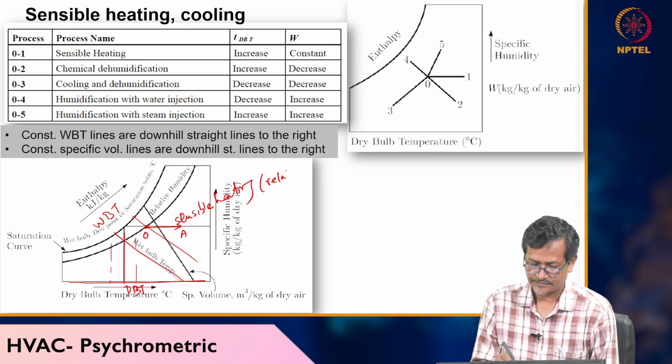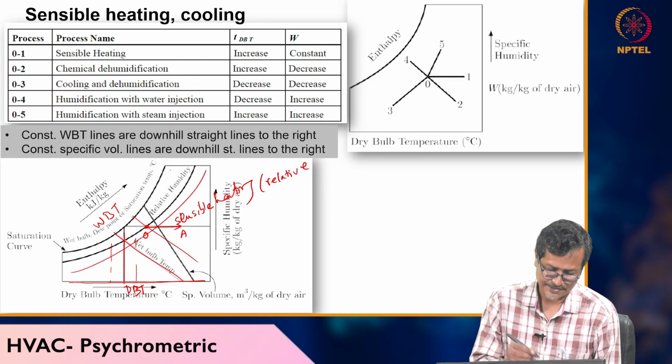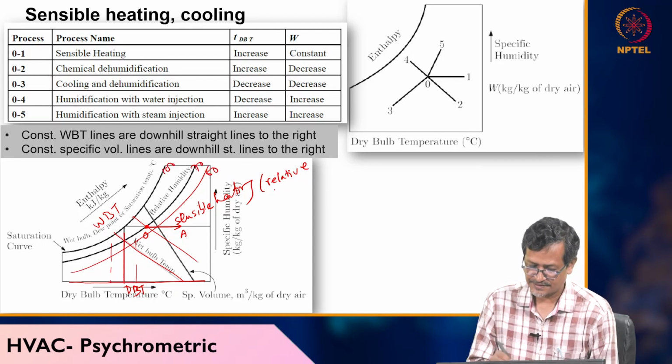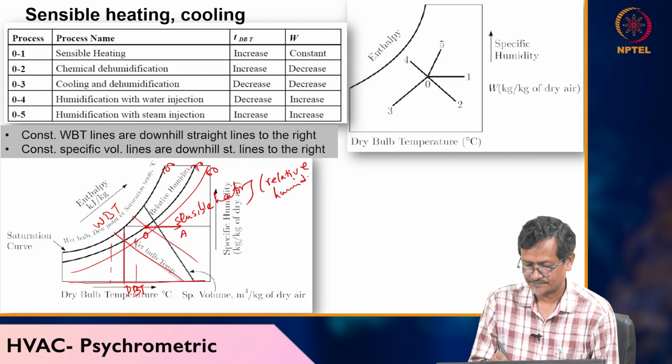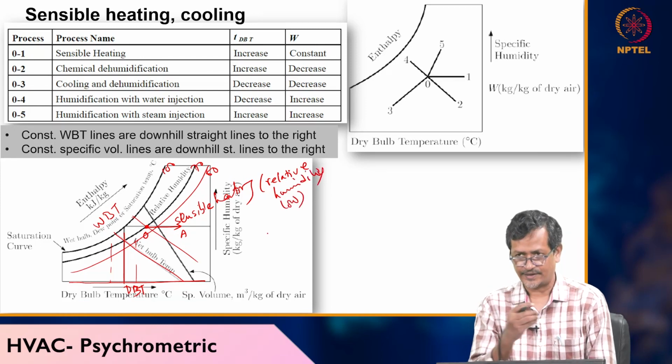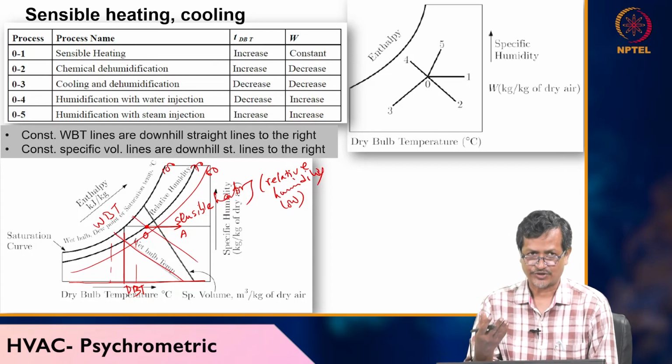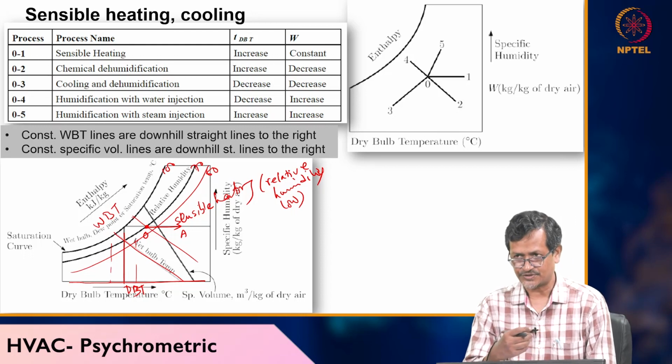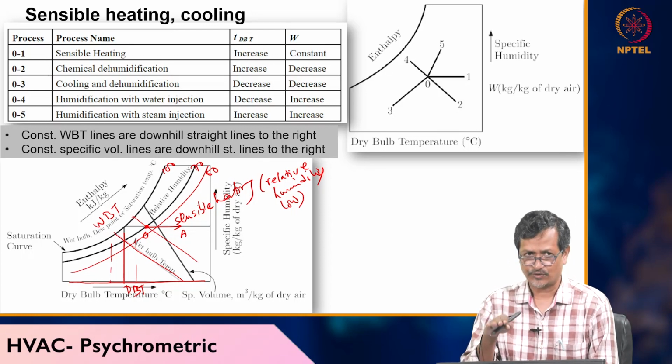Relative humidity, because you see these lines, 100%, maybe 70%, 60%, humidity lower. Okay, when you are heating, you are not adding extra moisture or removing moisture from the air. So in that case, your temperature is increasing, so your relative humidity will be lower.